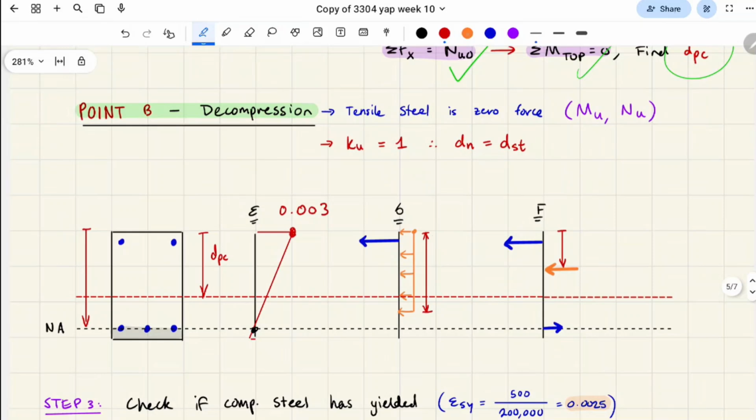That's alright. Here, this is alpha 2 fc, right? So we're using alpha 2 again. Once we have bending action, we use alpha 2, not alpha 1. Alpha 1 is purely compression. And here we're going to use gamma dn, so this is a rectangular stress block. This is a really big rectangular stress block because more of the concrete is in compression.